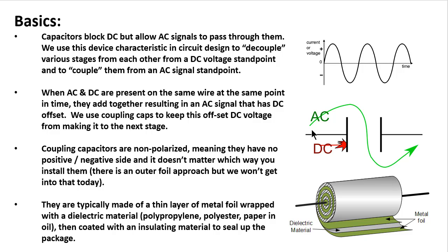And what happens over time is the chemicals inside of these start to break down, especially the old wax paper type. In other cases, the metal foil and the plastic that are wrapped up together start to deform because they draw moisture or heat or whatnot. And these capacitors start to break down over time. Once a layer of a capacitor starts breaking down and you get a little burn through to the next layer, it's a self-perpetuating failure at that point. In other words, it starts to disintegrate pretty quickly.